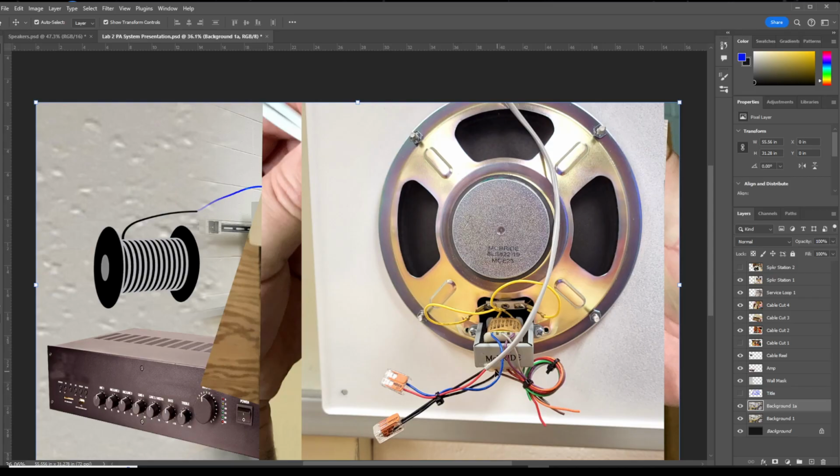So usually after you choose the 2 that you're going to connect, you're going to choose the black, which is common always, and you're going to choose one of the colors that corresponds to the wattage that you're going to tap in. What does it mean that, let's say, we're going to tap the speaker to 1 watt?